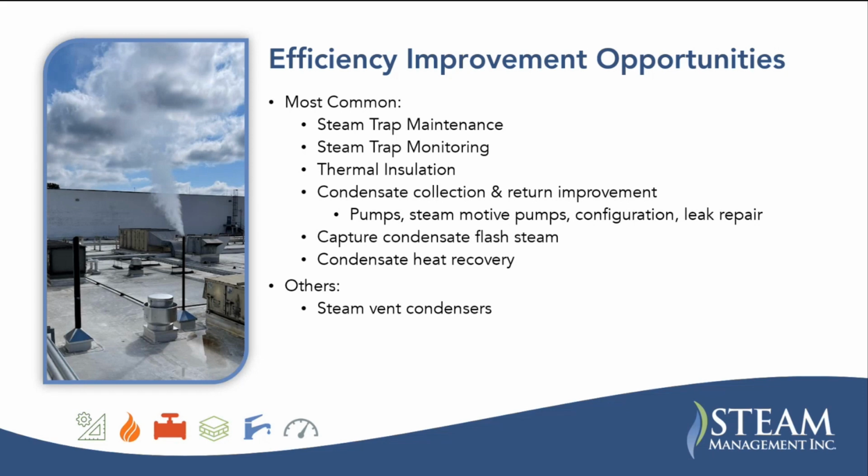Okay, so here we go. So most common efficiency opportunities are steam trap maintenance, steam trap monitoring, thermal insulation, condensate collection and return improvement, pumps, steam motive pump configurations, leak repairs, those can all be improved. Capturing condensate flash steam, condensate heat recovery, and also steam vent condensers.